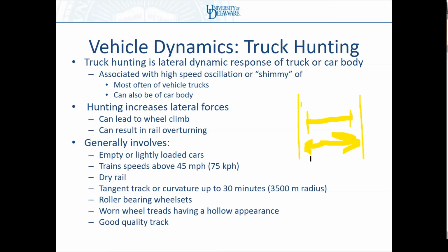Now, hunting is associated with higher speeds. And in fact, most vehicles, particularly vehicles that are designed to operate at higher speeds, like intermodal vehicles or passenger vehicles, truck hunting becomes a design criterion.